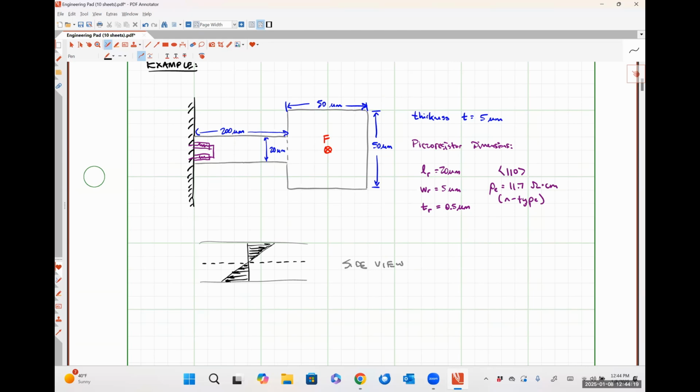Whereas if we made our piezo resistor dip deep into the bulk of this thing, it's going to influence the behavior, or potentially even worse, if we deposited our piezo resistor on top and it was thick and bulky, it would greatly change our stress profile towards the anchor.